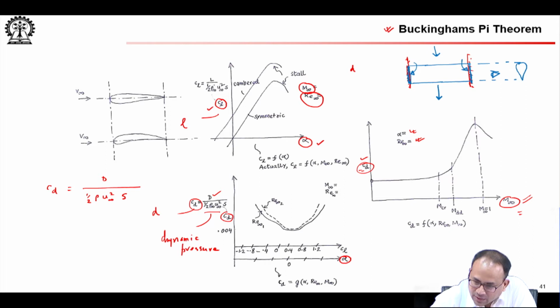Flush means it is almost sealed with this wall, so that there is no connection between the lower part of the wing and the upper part of the wing around the tips. If you introduce some smoke here, as is sometimes done in flow visualization, and you see some kind of a vertical motion happening, that means this wing that you have has not really been mounted flush.